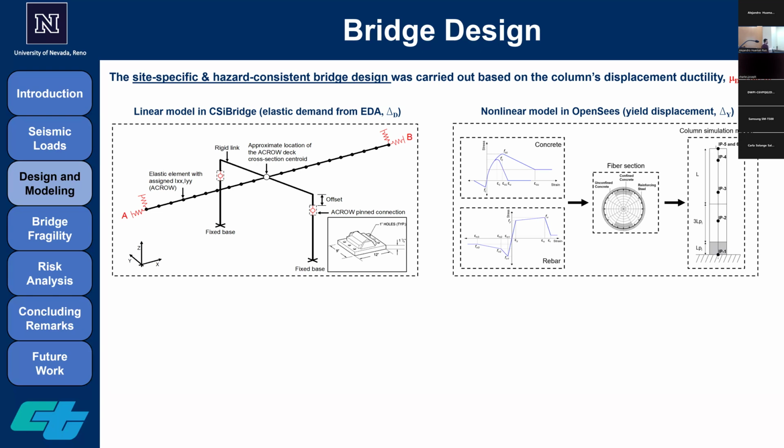And then we incorporate these materials into our fiber section to have a nonlinear section. For the element itself, as per request of Caltrans, we use concentrated plasticity. For concentrated plasticity, typically there is a hinge at the bottom or even top of the column, or both, and the remaining length of the element could be linear. But in our case, we use the remaining part again with the fiber definition to see how much the plastic hinge could spread along the length of the column. The plastic hinge itself was defined based on the equation provided by Caltrans, and we also check the value to make sure that the classification stays within the calculated value. The element itself is a nonlinear beam column.